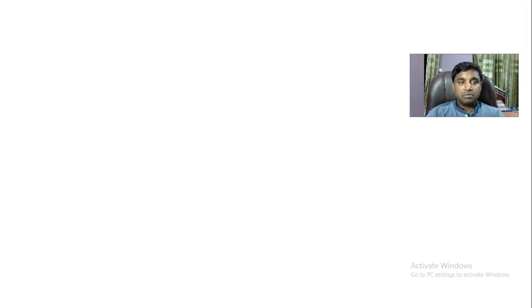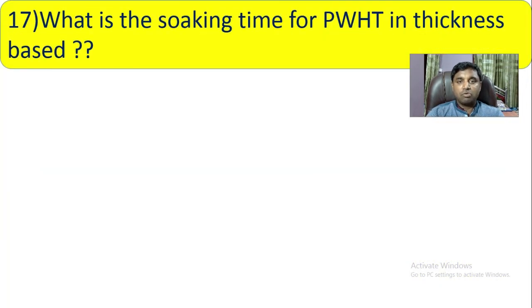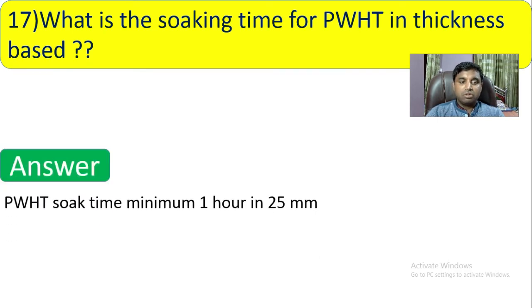Question number 16 finished. Question number 17, what is the soaking time for PWHT on a thickness basis? You know, the PWHT soaking time is minimum 1 hour per 25 mm. In 25 mm, 1 hour should be the soaking time.